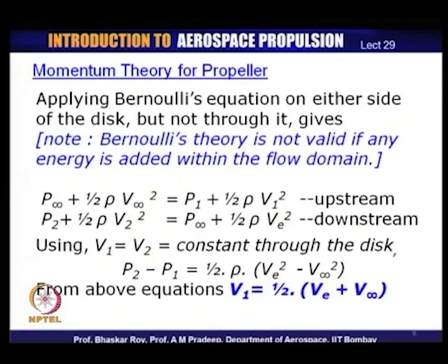Bernoulli's equation needs to be used on either side of the disk separately, but not through it, because the actuator disk is a working medium and it is energizing the flow, as a result of which Bernoulli's equation is not valid through the disk. So, this is one thing you need to remember, that you cannot use Bernoulli's equation if any energy is added within the flow domain.